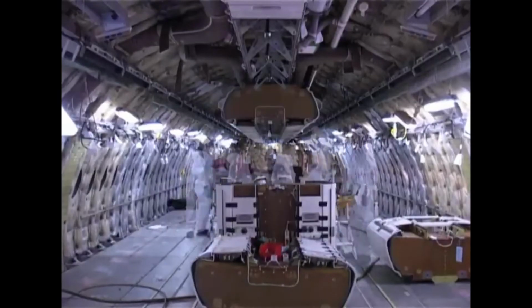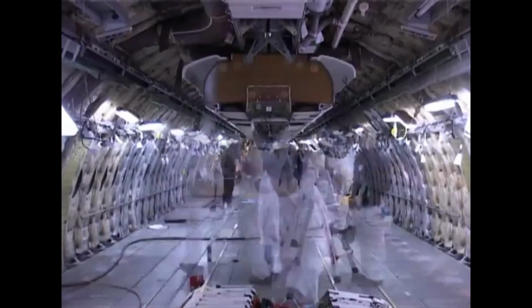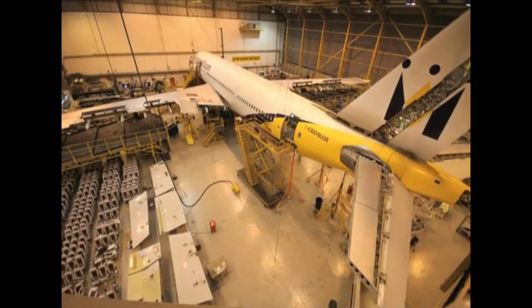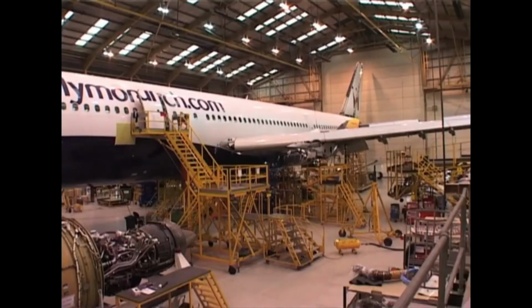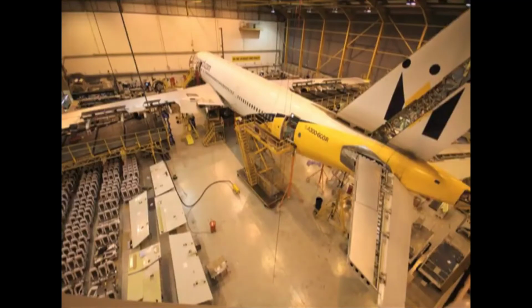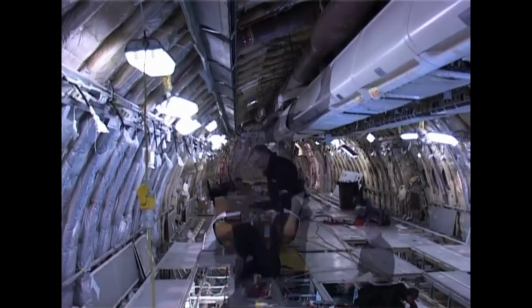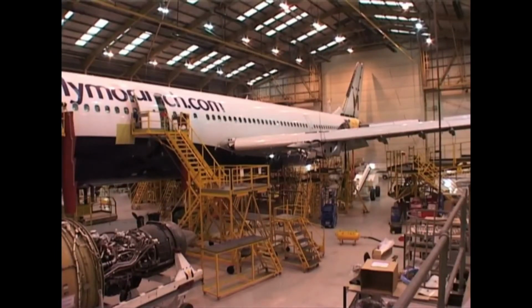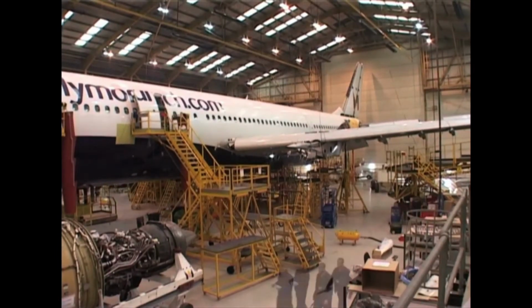Wrinkled skin, elongated or damaged bolt or rivet holes, or distortion of members usually appears in the immediate area of such damage, and any one of these conditions calls for a close inspection of the adjacent area. Check all skin dents and wrinkles for any cracks or abrasions.